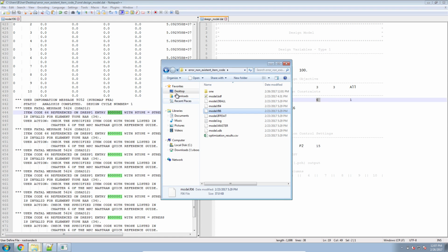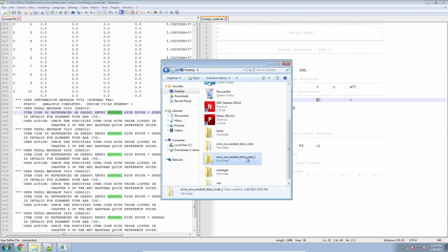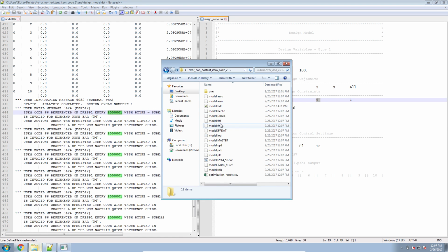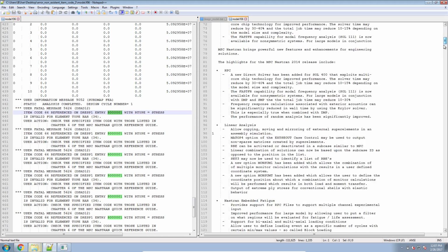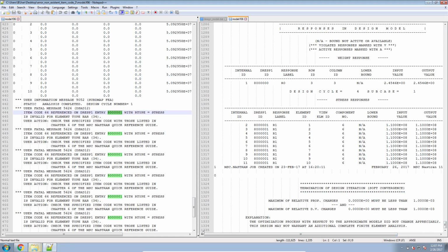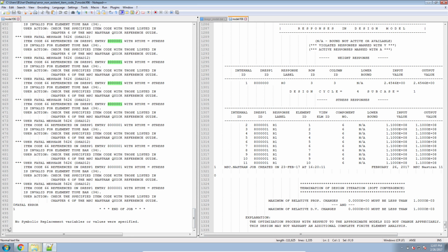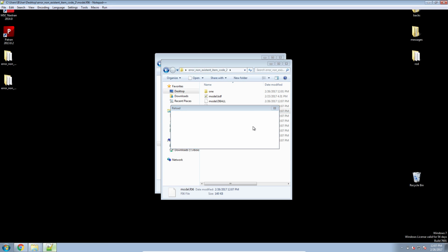With this, let's go ahead and look at our new F06 file, and the optimization is still happening, so the F06 file is not complete yet. But the first thing you'll notice is that the new F06 file is a lot longer than the old one. It gets to line 1335, whereas before we got up to line 499. So now there's more progression in the optimization. It's a good indication that the optimizer has made it farther than before.